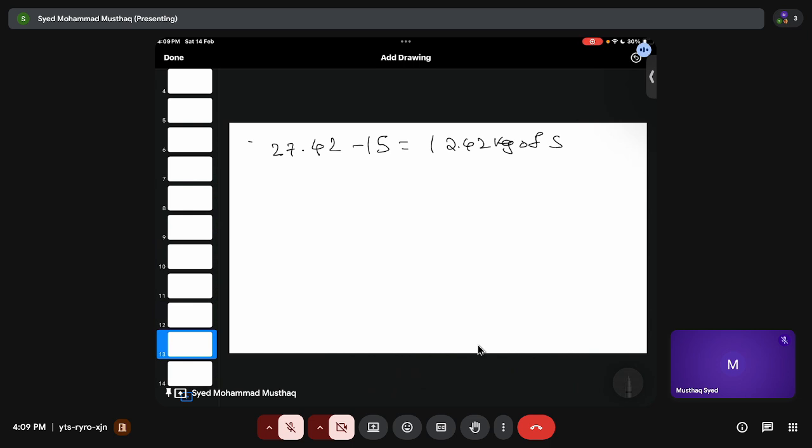Now in the question they have given that H2S is only 1.84% of the coke oven gas. If we don't know that, then we cannot do it, right? So we need to know at least one composition of the gas. So 1.84 of coke oven gas. Let's do everything in meter cube, not involve liters.